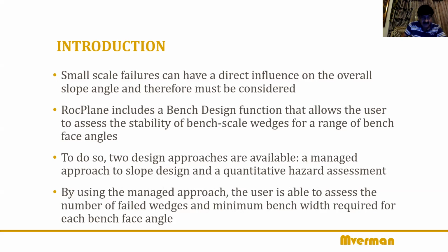And RocPlane, which is what we're going to discuss, includes a bench design function, which allows the user to assess the stability of bench scale wedges, the wedges formed at the bench level. For a range of face angles, you can change the face angle and see how the wedges are formed, how these wedges are affecting the stability at the benches. For doing so, two design approaches are available. One is the managed approach to slope design, and the second one is a quantitative hazard assessment.